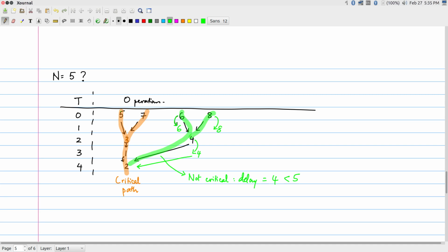They can't be moved. In my original schedule, of course, the one that is written in black, 5, 7, 6 and 8, all the multipliers are scheduled at time 0. The only way I can do that is use 4 separate multipliers. Okay, so as things stand right now, with my original schedule, 5, 6, 7, 8 are all scheduled at time 0. I need 4 multipliers.